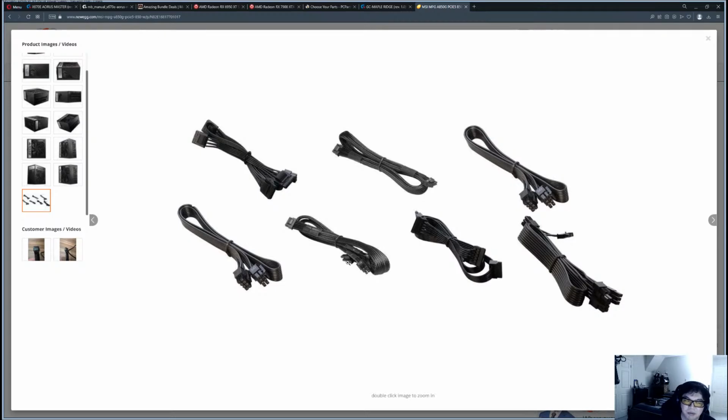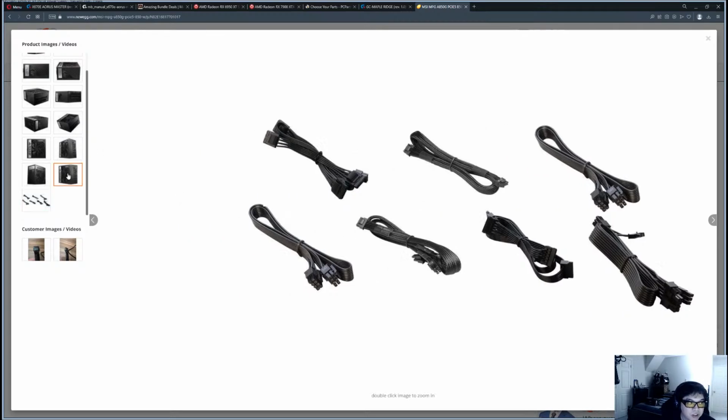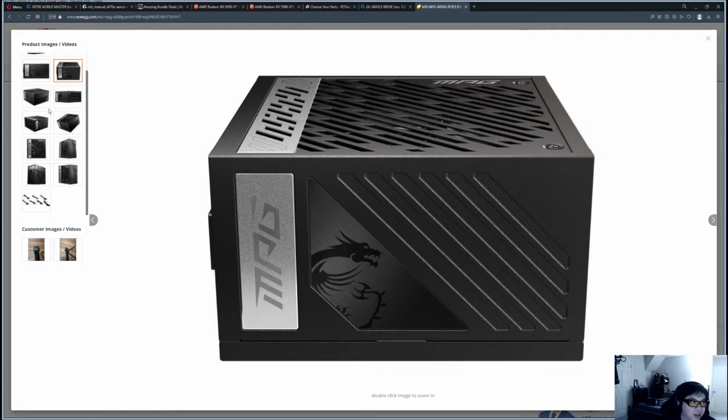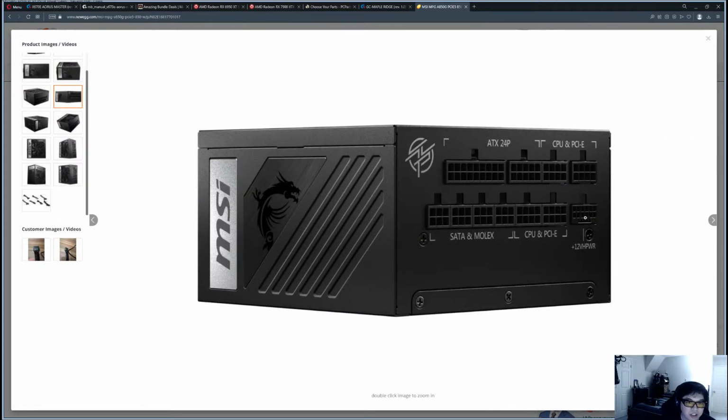So you'll need this cable. Well, you don't need this cable, but if you wanted to use this power supply with that graphics card, you would have that cable connecting over here, and that would give you 2 8 pins to the graphics card. Then you'll need to use another separate 8 pin up here for the third one, and then you still have the 1 or 2 for the EPS 12 volt to the motherboard. So that's something to be aware of. So this power supply would work.